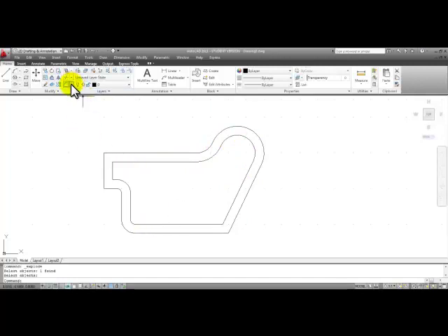Now we can use the fillet command in the modify panel. Right click and pick radius. Type in 0.5 and enter, and select here the angled line and the horizontal line on the inside here. Save your file, and that is the Gasket Design detail.